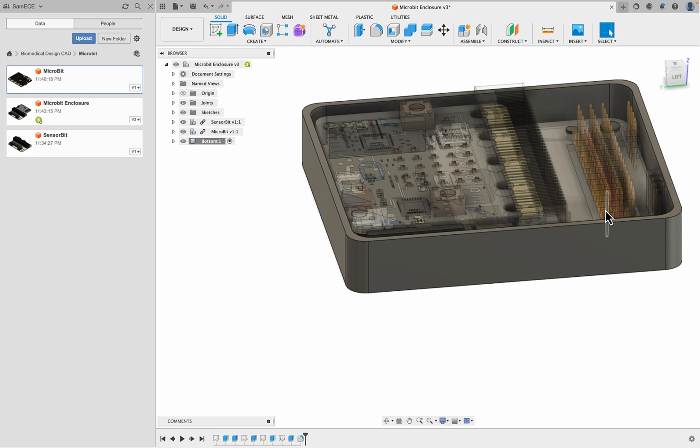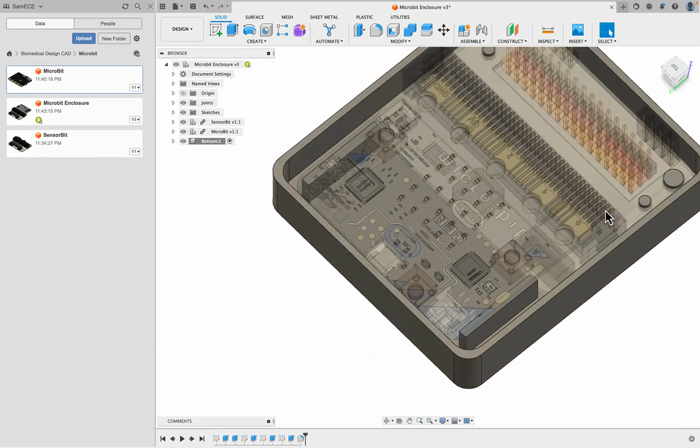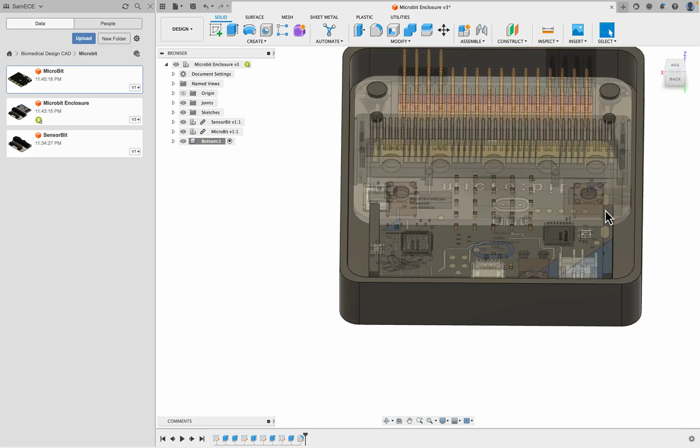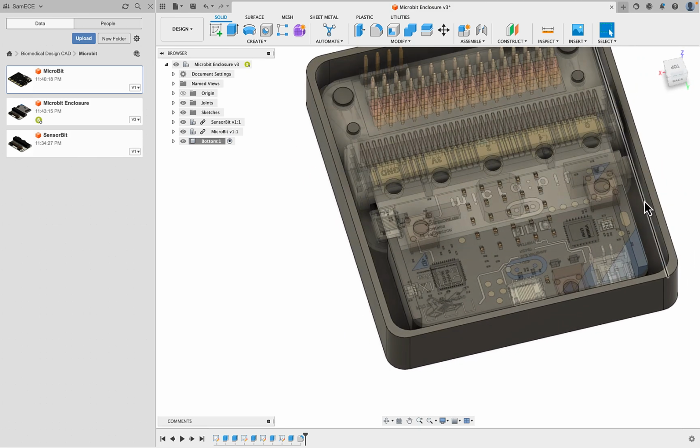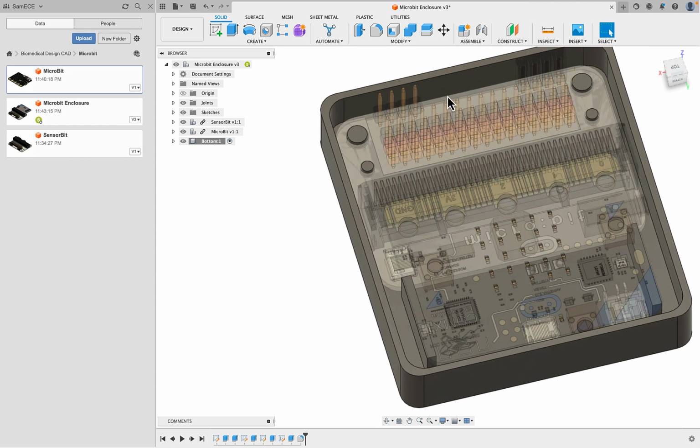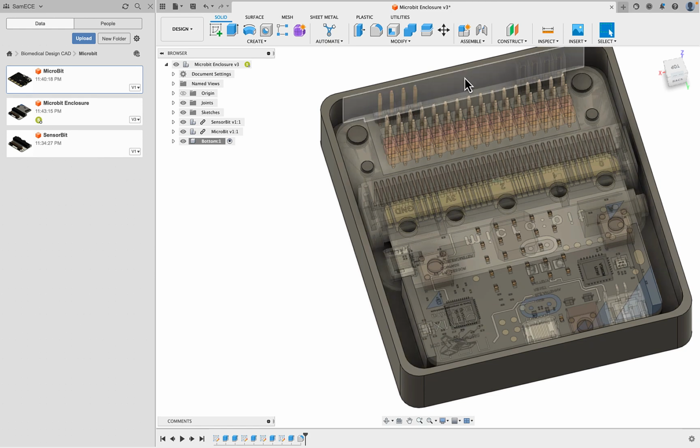There are a great deal of ways in which to do this. One would be to create a snap fit, and I think that might actually be a good choice here. So basically let's do some studs on the top one that goes into a slot here, here and here. So that means it'll lock into place and, well, somewhat into place.